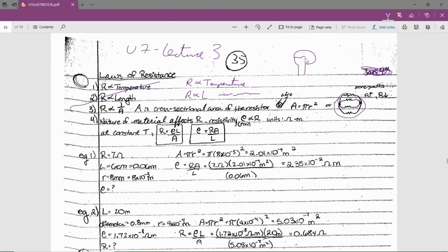And think of the filament made out of tungsten, right? So there's the filament. So when you have a current going through there due to friction, you're going to get a resistive heating. So the heating is going to increase the temperatures. The resistance will go up, but it will also cause the filament to start melting a bit. So it's going to get thinner. If it gets thinner, well, then the resistance is going to go up as well. So those factors work in a cycle till eventually the filament snaps and you've lost your light bulb.